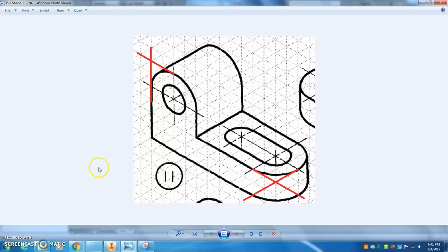Okay, we're now ready to start making some more complicated shapes using some more advanced techniques. So the first object we're going to make from another sheet of shapes called 20 more ISO shapes is this object, and it's called shape number 11. So a number of things we're going to learn here: how to round these edges and how to make a cutout with this shape and locate it on the place that we want it to be.